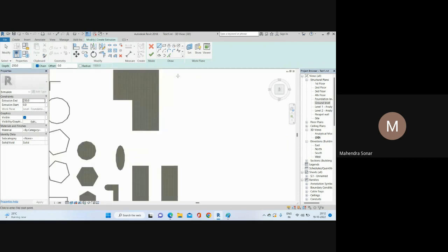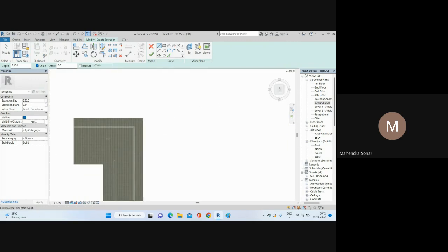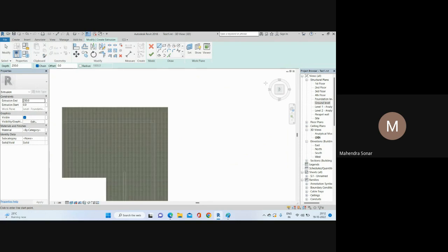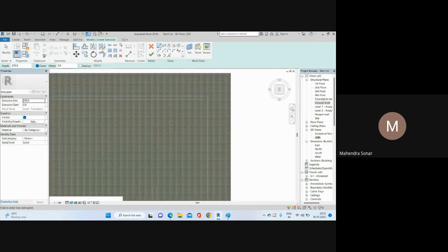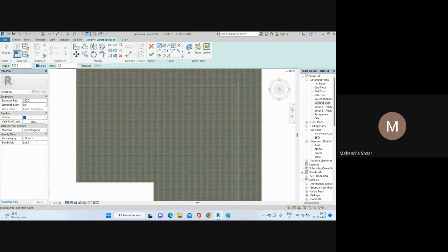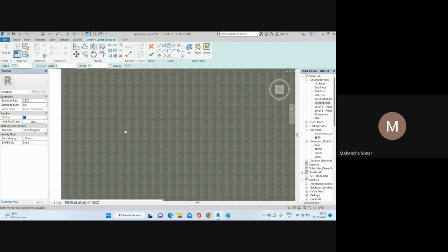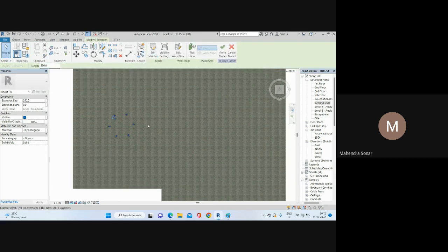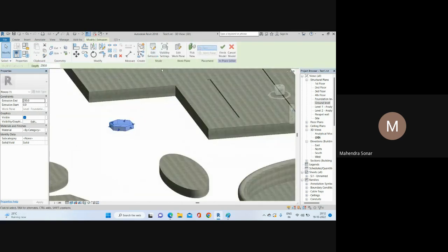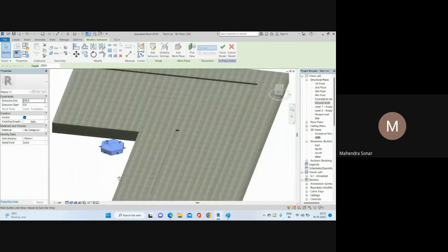So if you use the vertical or horizontal extrusion, you can just set your path, no need to set the plane. Okay, so I want to create some shape void here, so I will use this option and just add this shape. Okay, so once you complete your shape, so you just click here OK. Okay, then after that you can see your shape is created here.